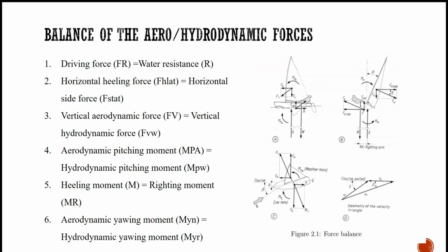So we can conclude that the driving force is equal to the water resistance, the horizontal heeling force is equal to the horizontal side force, the vertical aerodynamic force is equal to the vertical hydrodynamic force, the aerodynamic pitching moment is equal to the hydrodynamic pitching moment, the heeling moment is equal to the righting moment, and finally the aerodynamic yawing moment is equal to the hydrodynamic yawing moment.